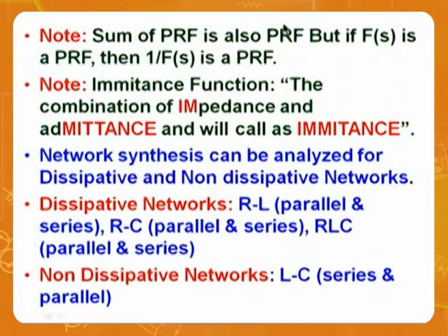Every function should be PRF before it is really synthesized. If it is not PRF, don't go for synthesis. It is all waste of time and waste of money. Then note, sum of PRF is also PRF. If f of s is PRF, 1 by f of s is also PRF. That means if the impedance function is PRF, admittance function is also PRF.